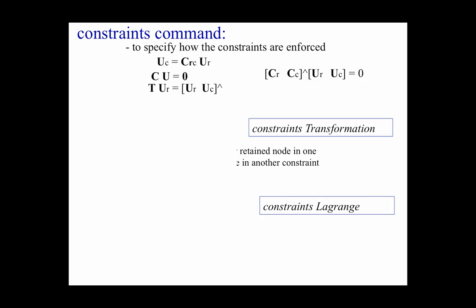So this is actually the equation you're solving when you use Lagrange. And if you're using the penalty method, AX equals B is basically the original structural matrix augmented with this C transpose alpha C, where alpha is our penalty factors that you specify in the command. The right-hand side also has some forces, but these are typically equal to 0 because that Q matrix is typically equal to 0 for our systems. So we're basically dealing with this.